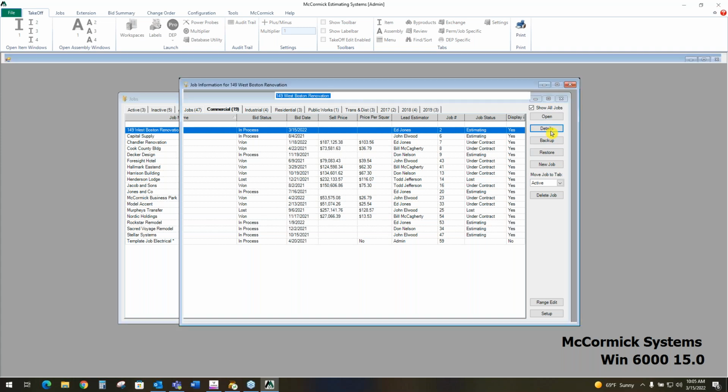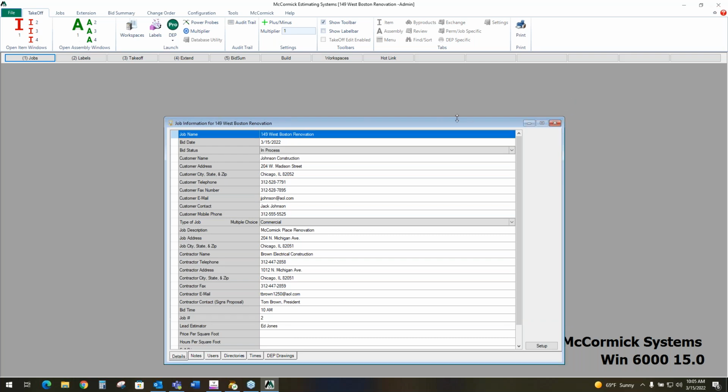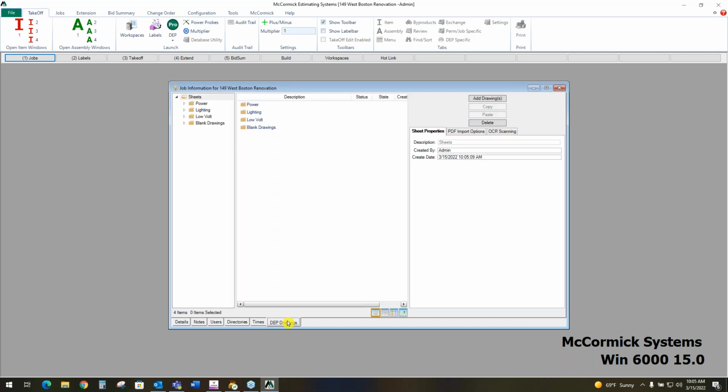Step one is putting in job details. With the integration with Foundation, these job details are going to flow into the accounting side of things. So everything you put in here in McCormick is going to auto save. The big thing you do in step one is bring in any digital files that you have to bid the project with. So this is where we're going to get them off of your computer, maybe where you've got them downloaded somewhere on your network. We're going to be able to add all of our drawings, blueprints right here in step number one. So that's really the big thing that happens in step one: job details, bringing in your files. Then it's a 5-step process. You're going to work your way through these 5 buttons up here in the top ribbon. It has a real simple flow to it.